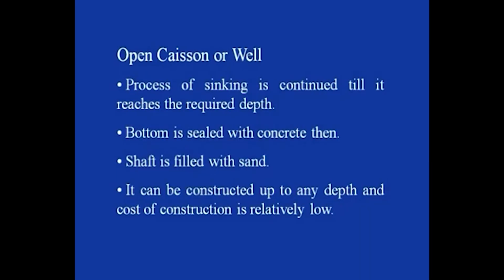Now coming to some of the features of this open caisson or well: the process of sinking is continued till it reaches the required depth, that is, what you have obtained from the design consideration and the bearing capacity of the soil stratum.